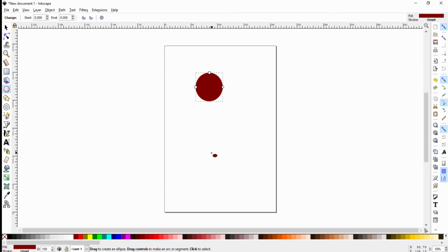If I want to create an ellipse, just like I was able to create a rectangle that kept proportional width and height, I can do the same thing with a circle, make it into an ellipse by holding down the control key. And as I start to build a circle, you see if I drag to another dimension to the right, I create a perfect ellipse that is 2 to 1 proportionally, or if I keep going, it'll be 3 to 1.